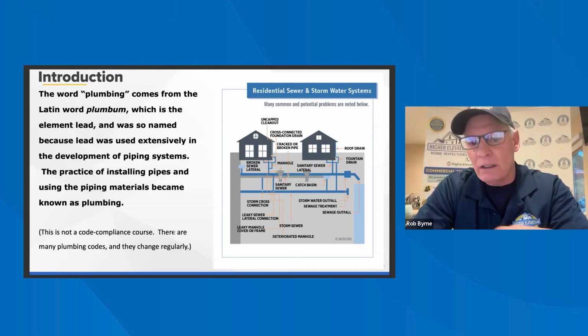read it, because if you come across one of those water heaters, you'll see it says, have it inspected annually, and they'll tell you. So when I talk to my clients, I explain to them, when you have your service, just make sure that the plumber is checking this for you, because what that does is this corrodes and deteriorates, and it's exactly what it's called, a sacrificial rod, so it doesn't affect the tank itself.